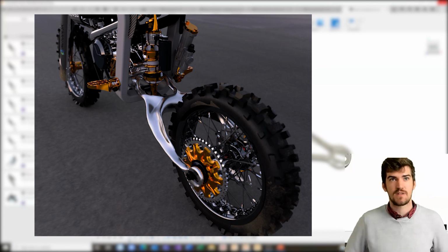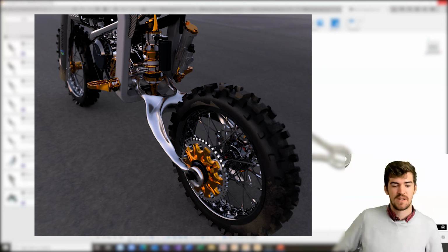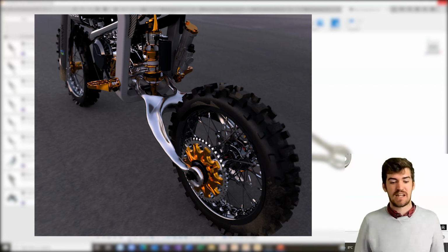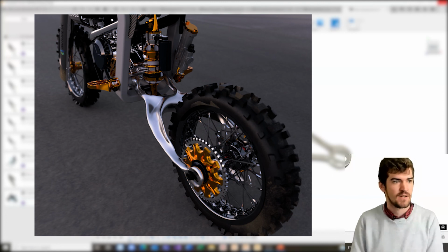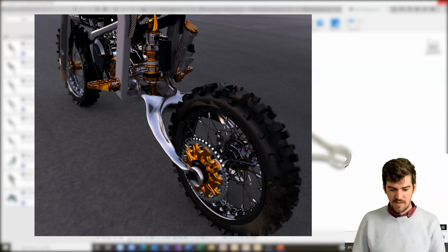What I would say though is you want to try to keep the preserve and the obstructive geometry as simple as possible. If you were going to be bringing in the wheel, it might add a lot more complexity to the final study. So you want to keep the geometry as simple as possible and push that into the study itself. Perfect. Thank you, Karen.